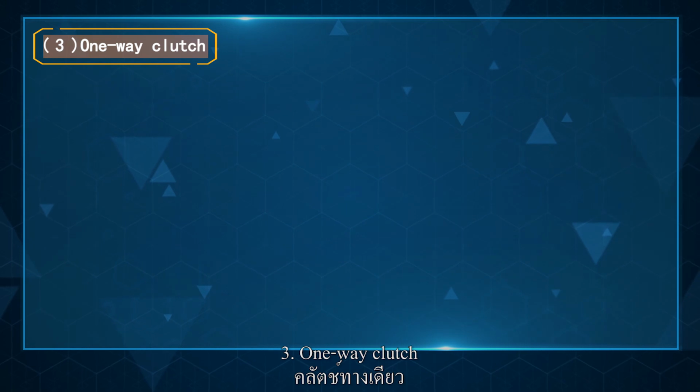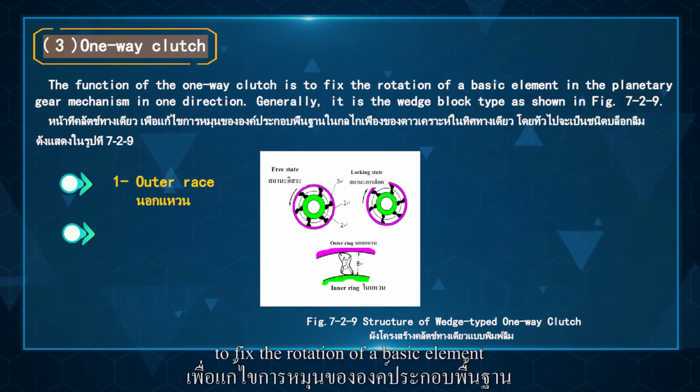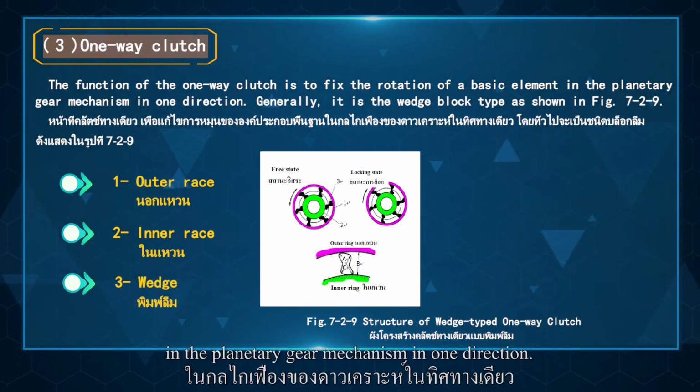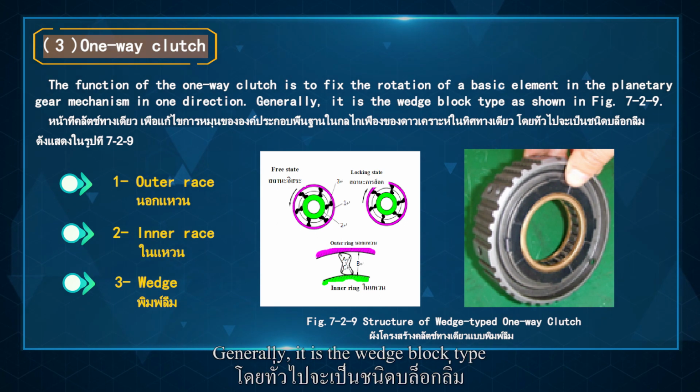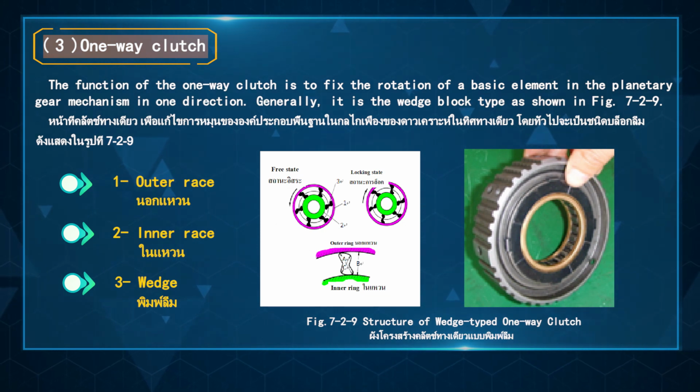3. One-way clutch. The one-way clutch is used to fix the rotation of a basic element in a planetary gear mechanism in one direction. Generally, it is the wedge block type, as shown in figure 7-29.